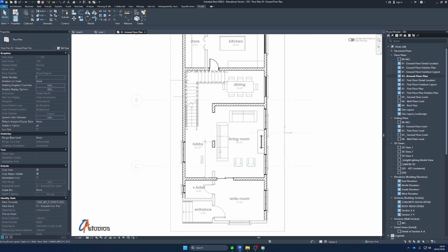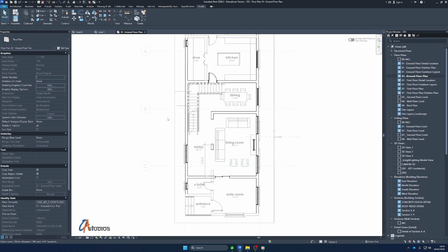Okay, so for like the detail elements per se, the grids and the crops and all, I don't have to zone in into one particular view. I'll do it in 3 views rather. So I would clean up one view before I duplicate it, and then I apply the design options to the views. All right, so let's do that.